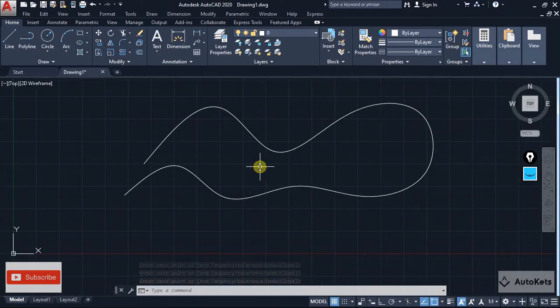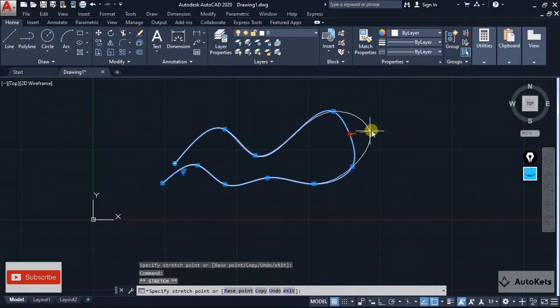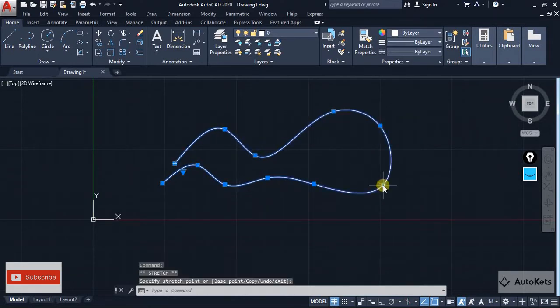So you can see that this is how you create the spline, and this is a spline fit, which is the first type of spline. If I click on the spline, you can see that there are other points. The places where I have clicked my mouse button, you can see that the points are created, and with the help of these points, you can control the spline. Just click on the points and it will again dislocate the spline, and accordingly, you can fit the spline like this.